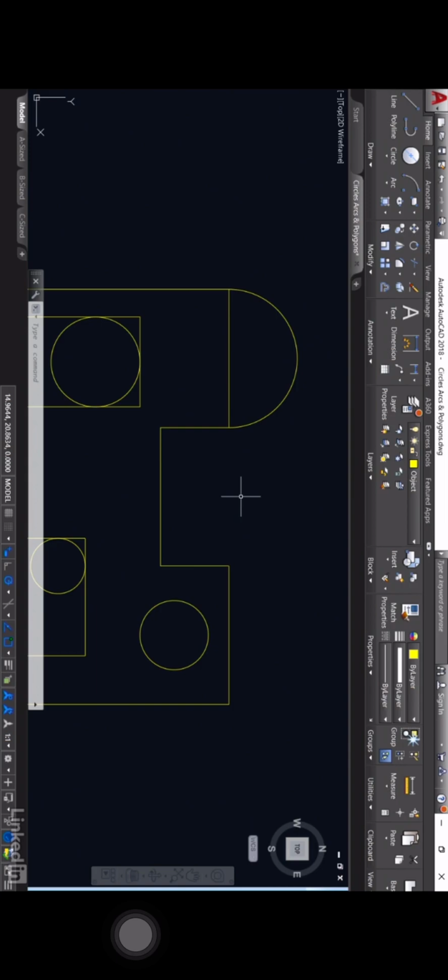Now, what about this fillet arc I mentioned? If I go to the Modify panel here, click on the flyout here and select Fillet, like so. If I come into the drawing area now, if I hold down the Shift key on the keyboard and then select this line and this line, it automatically gives me an arc because it's filleting those 2 ends of those 2 lines I selected. But it'll only do that if I hold down Shift, or will it?